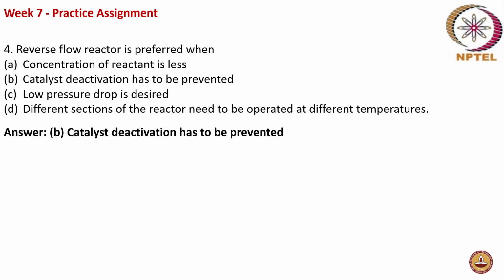So when it goes through the inlet, the temperature slowly increases in the inner diameter, and when it goes through the outer diameter, as the reaction proceeds and the reactant flows out, the temperature in the inner tube is transferred to the outer tube, or from the outer tube to the inner tube. So there is a heat transfer between the inner and outer tube, by which the temperature support can be given and an autothermal operation can be maintained, thus helping in increasing the reaction rate by giving a preheating operation.